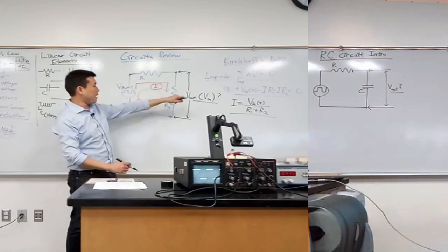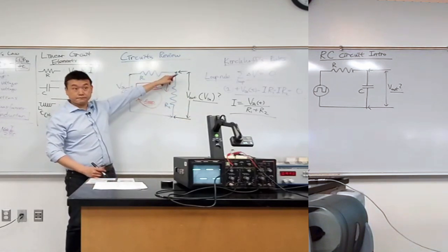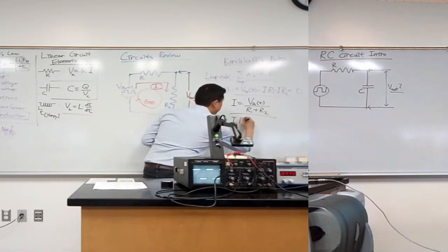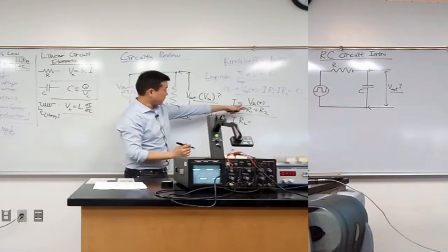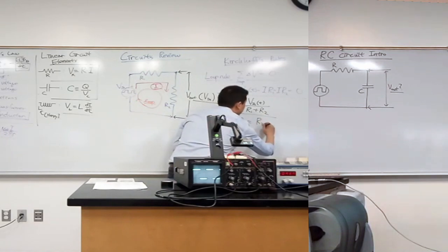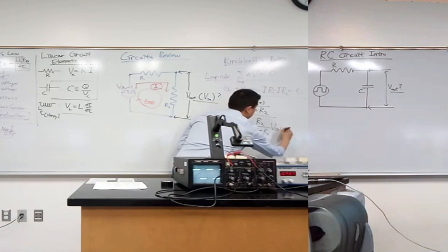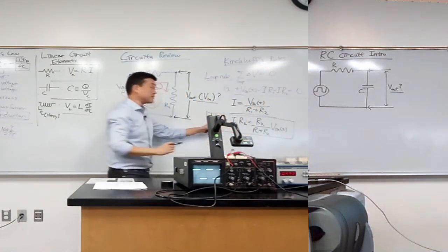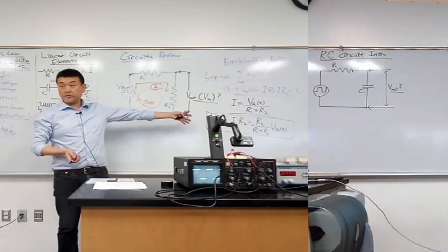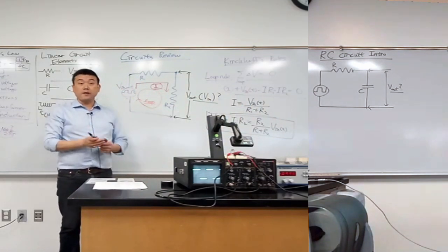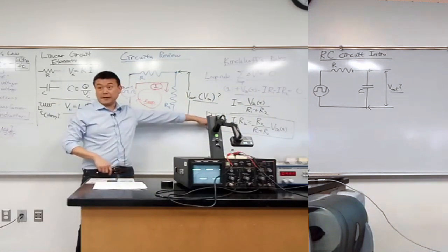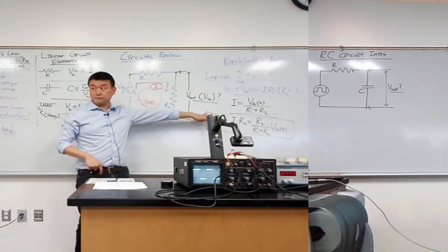As Chris said, multiply the current with the resistance. So that's going to be my V out: the current times the resistance R2, or plugging this in, it's R2 over R1 plus R2 times V in as a function of time. But I'm hoping all these results sound familiar. It's the voltage divider equation that you have seen in homework, and I thought you have seen it elsewhere too. You have seen this multiple times. This is a familiar expression.